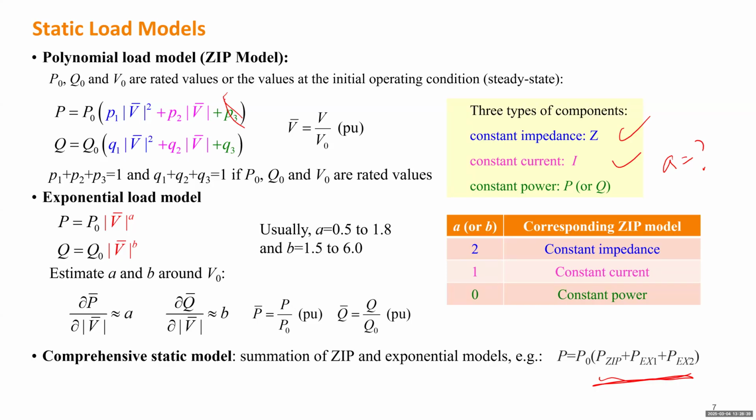Yeah. So for the exponential load model, we are trying to find out A and B. P0 and Q0 we already know, those are the base values.